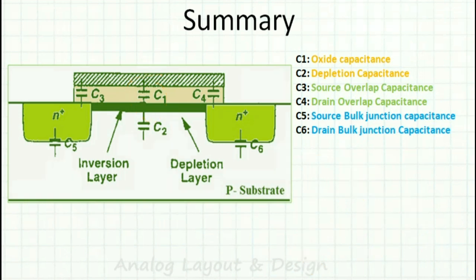And then we discussed about the overlap capacitances. Here ideally the drain should have been only so much, but then there is a protrusion under the gate, so that's why we have the overlap capacitances between the gate and the source and gate and the drain, which normally we will show like this, as the CGS and CGD, sorry, and this is the CGS. So that's about the overlap capacitance. This one we didn't discuss much, that's fine.